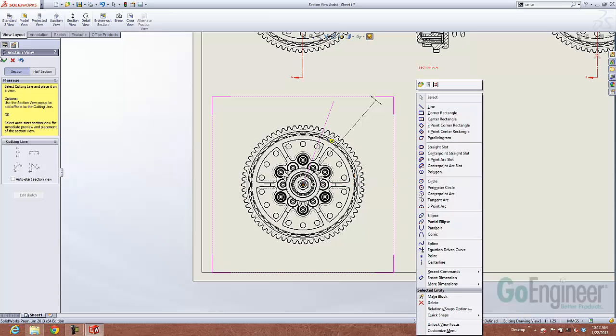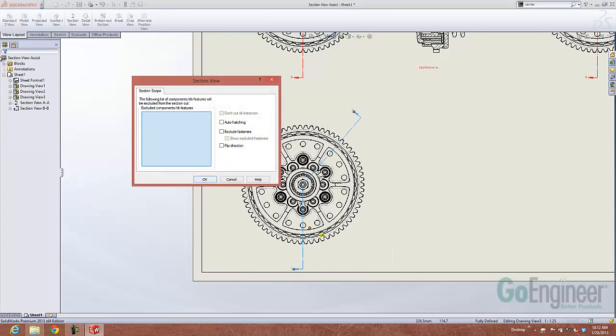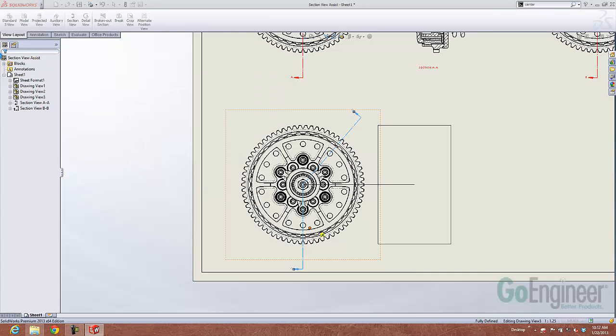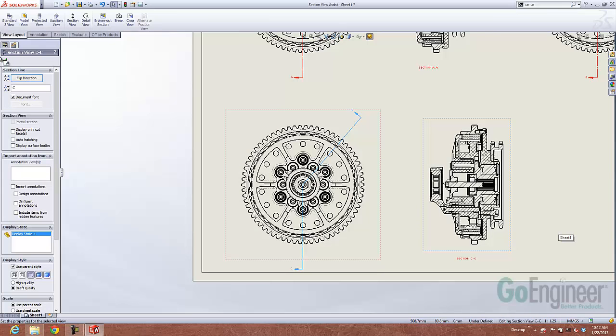And we'll back up. I made a little mistake there. So we'll place him in here. We'll place him through the center of that hole, and then make sure that he's going straight down or lining up with the center of this hole. In my checkbox, I can add additional jogs, but we'll just hit the checkbox in here. And it's created that section view.